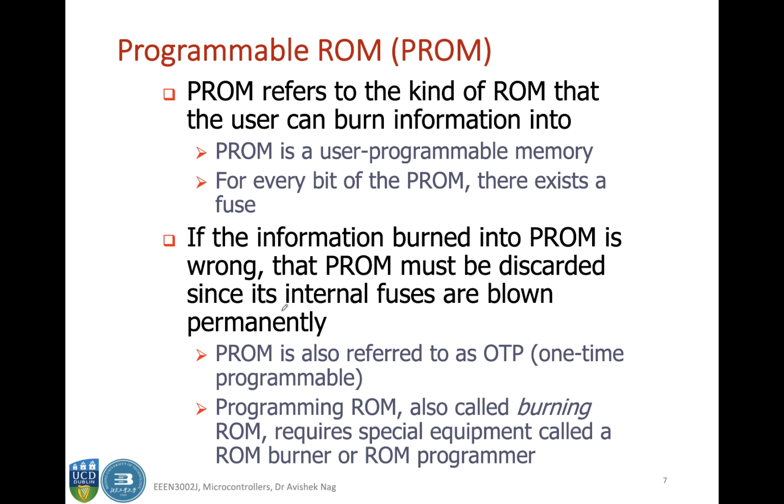In case of the programmable ROM, or PROM, you have programmability associated with it. A user can burn information into it. PROM is user programmable, and for every bit of the PROM there exists a fuse.